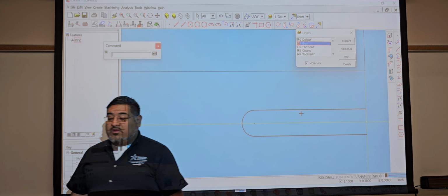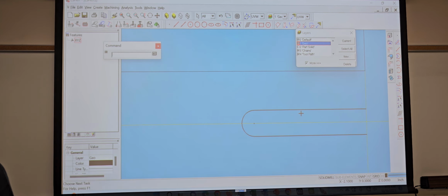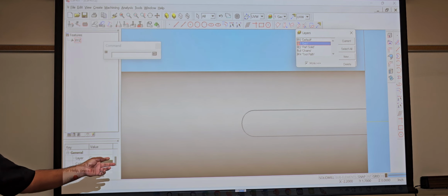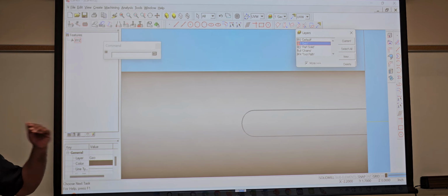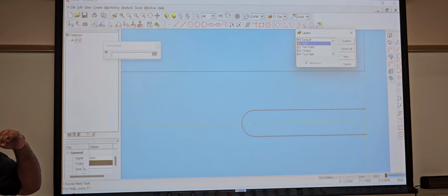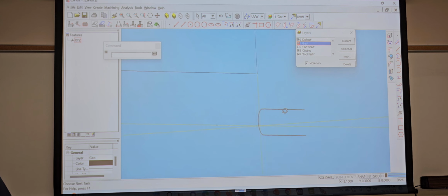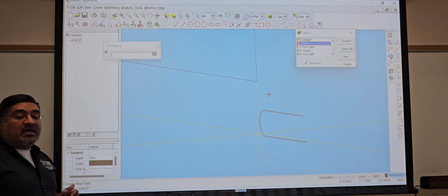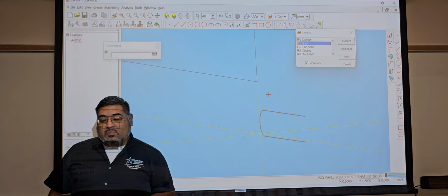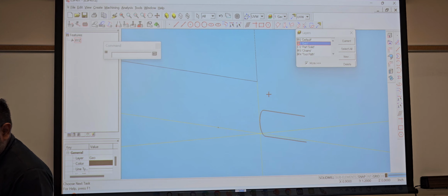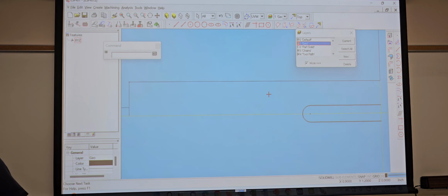right? How you could confirm that that actually happened is one, if I click my solid, I should see it, right? Because if I left it down there, it wouldn't click up here with my solid, correct? Or just hit control, put the wheel of the mouse down, go sideways, right? So two ways to confirm that that actually came out, correct? So it's out now, so I'm just gonna hit F7.